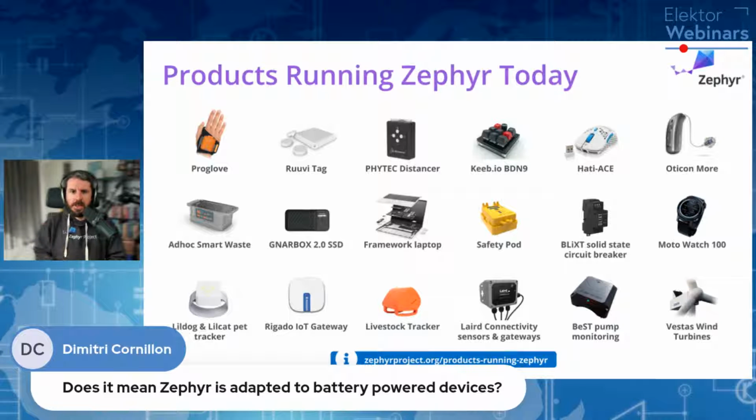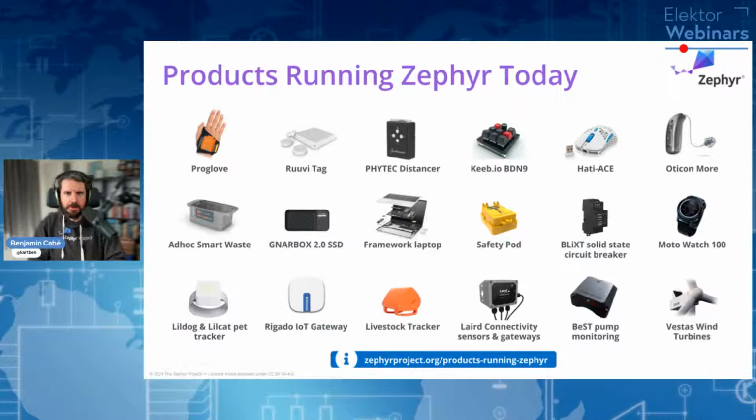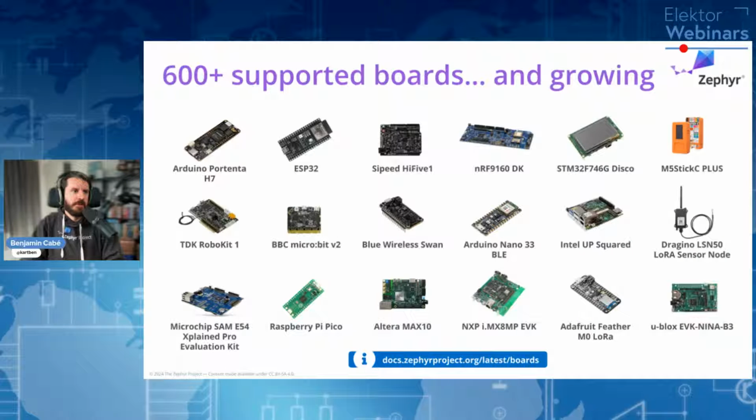You schedule tasks to run at a regular interval, like every 10 seconds, acquiring temperature data from an I2C sensor. 99% of the time, the device will just sleep, then wake up every 10 seconds, wake up the I2C peripheral and whatever code and peripherals need to be woken up, do the work, and then go back to sleep and back to just a few microamps of power consumption.